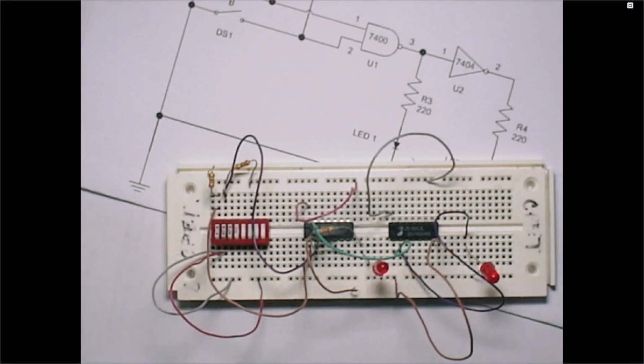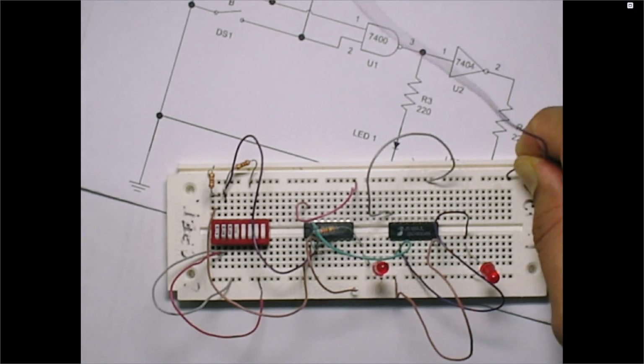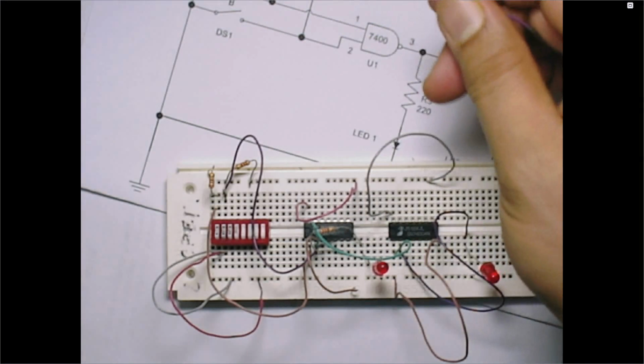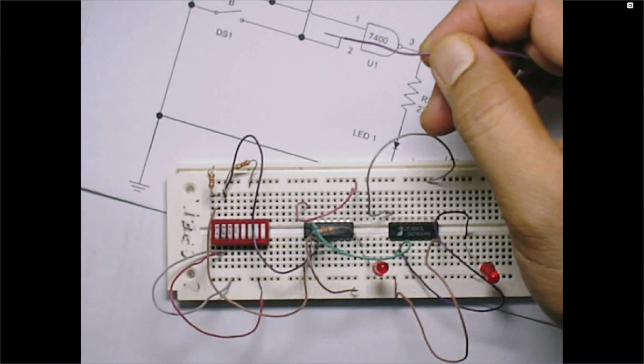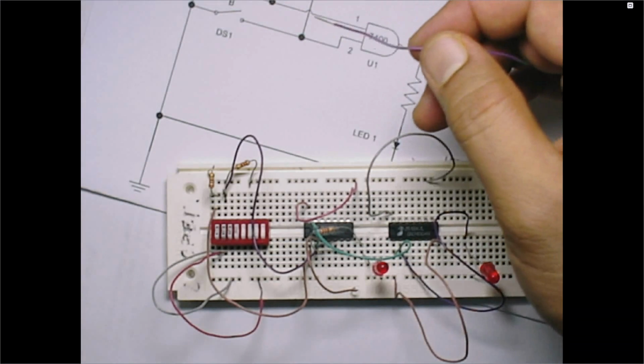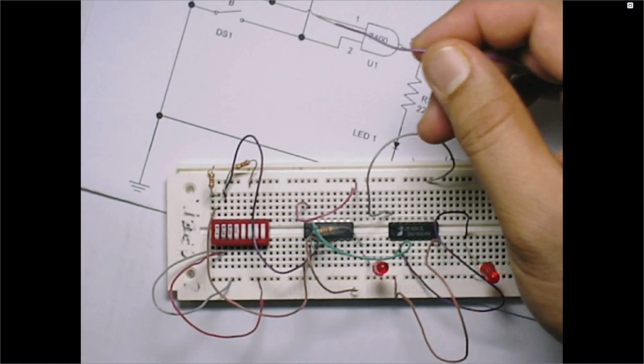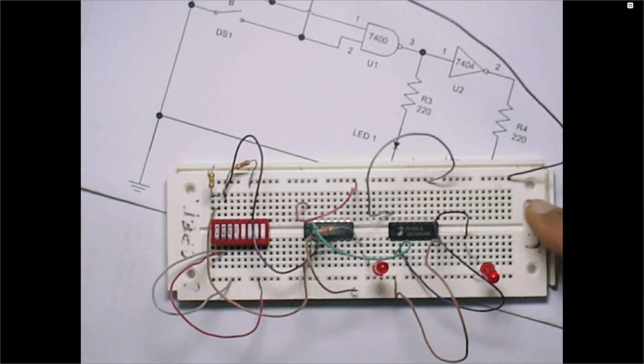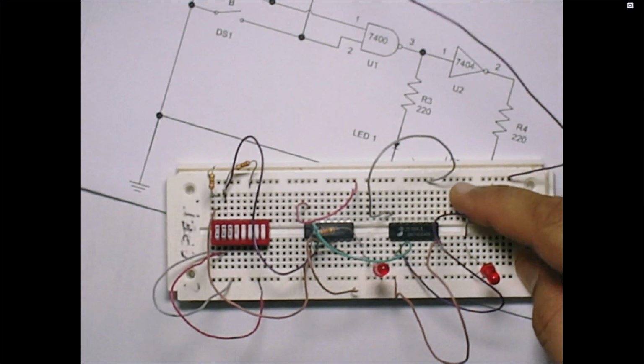Now once you go to the lab, you will need the power, right? That means you will need the VCC to be connected at the top row. So you will be leaving a wire like this, open on one side, and this open side will be connected to the voltage 5 with the alligator clip. Once you go to the lab, you will find some alligator clips. So connect the alligator clip with the voltage 5. This will be your voltage 5 because this is connected to the top row, and the top row is the VCC, right?